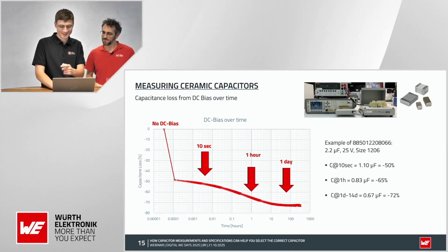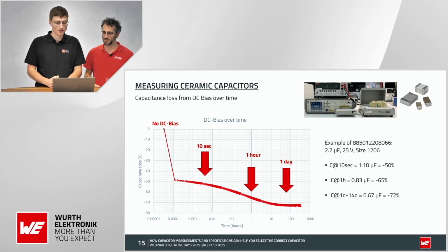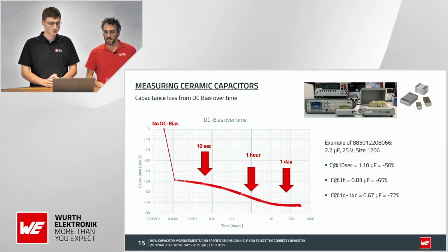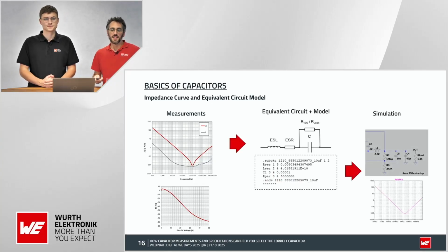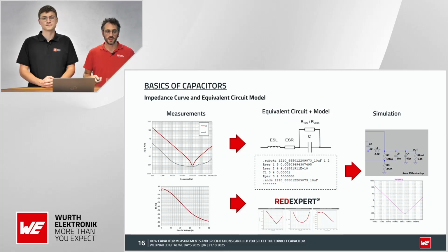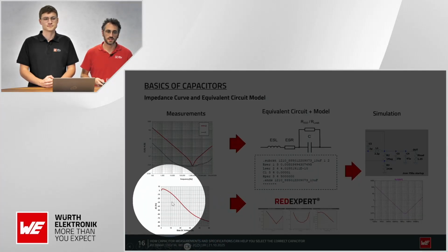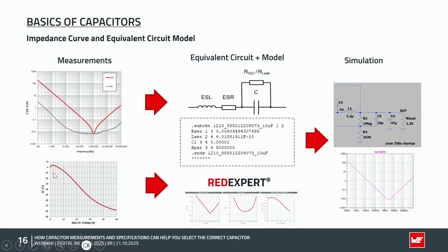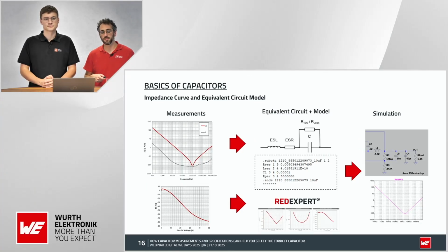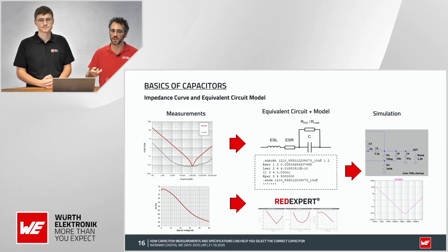Next question about slide 16. Is the DC bias aging effect included in the SIM model? Can you reconfirm? No, actually the same slide. In our model, what we have is this curve. So this is taken more or less at 10 seconds of loading the capacitors. So the aging of DC bias is not included in the library because we don't know how long you will have the device on.